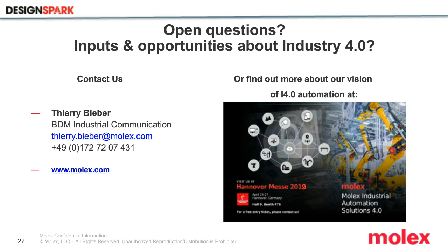And new kinds of devices like these edge devices can either process this data, or if the amount of data is bigger, the edge gateway will collect this data and send it to a cloud, into a database, and you can then process this data afterwards with dedicated big data mining software to recognize patterns and different interactions between parameters, detect relevant patterns for the health of a pump or of a drive, and so afterwards really monitor for this specific pattern in order to recognize and detect a defect earlier.